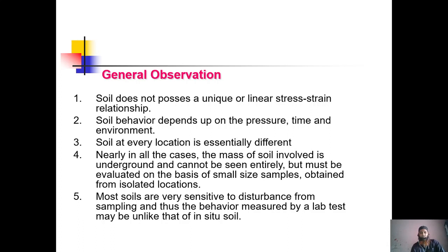So the soil does not possess a unique or a linear stress strain relationship, as I told you. Whereas we have in steel a linear stress strain relationship. The same way that cannot be achieved here in soil. The soil behavior depends upon the pressure, time, and environment. So depending on the pressure coming onto that soil, there might be changes, and depending on the time also. How it is placed, at daytime or night time or summer time or winter time, all this also plays a different role here.